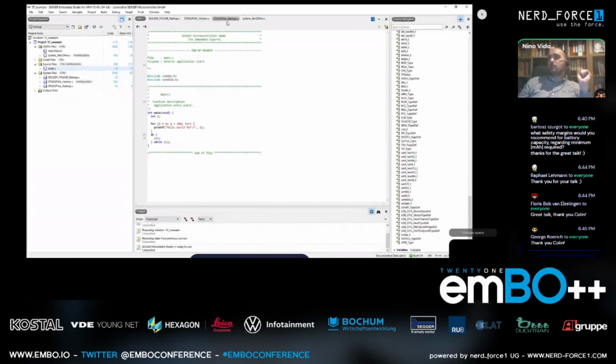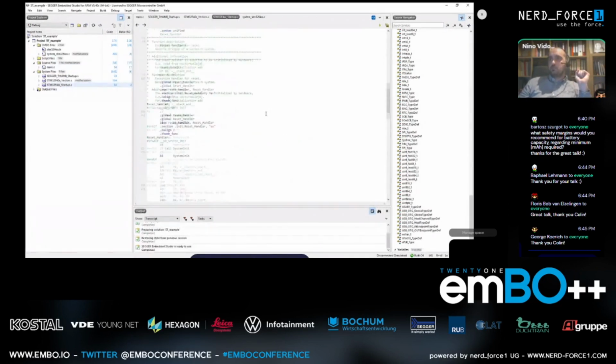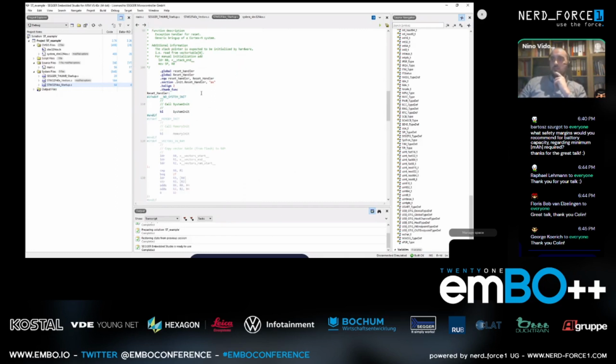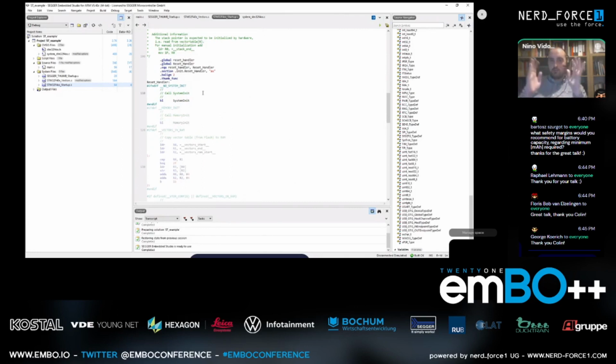If we look at the entry point for Cortex-M, it is the reset handler. So we go here into the reset handler. Essentially, after the target resets, it will boot from address 0 usually, and will read the stack pointer and the PC where the reset handler is located, and it will jump to that location, and we end up here in code. The first thing you see happen, and don't be scared, I know this is assembler. Many people are scared of assembler. Don't worry, I will talk you through it and nothing will happen to you.